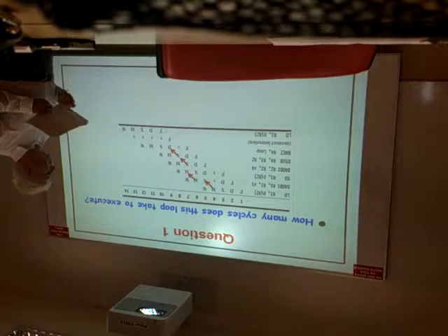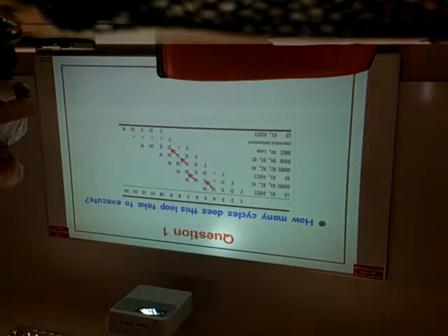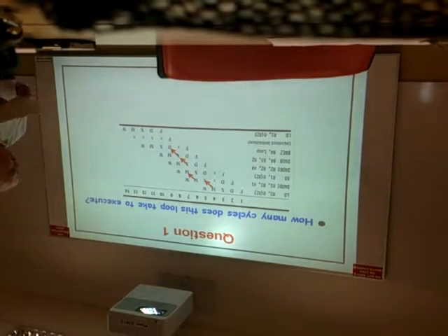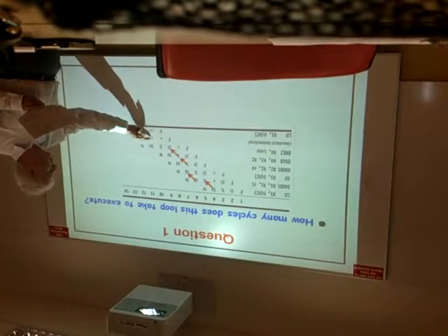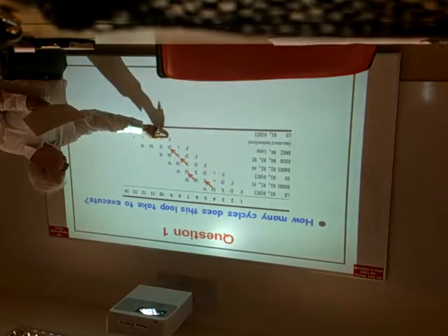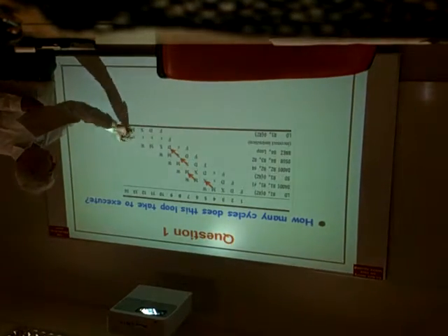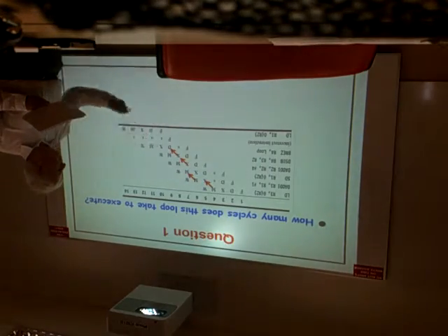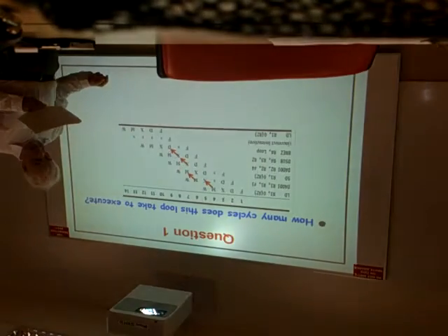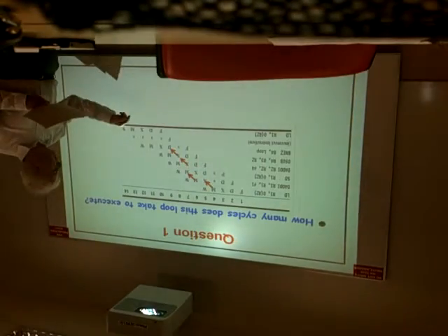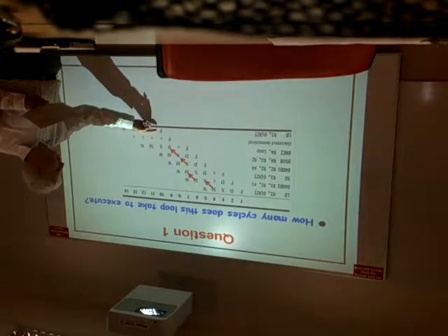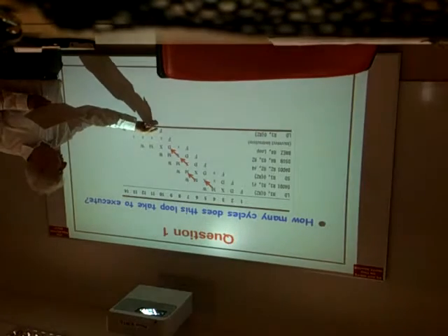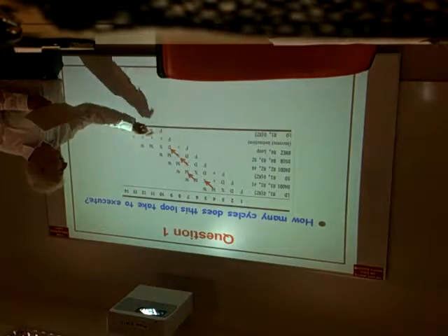And then for the branch itself, we predict the branch is not taken. So if we predict the branch is not taken, we will actually get the incorrect instruction. The branch is resolved in the decode stage, and the PC is updated in the decode stage, so we can actually execute the fetch for the correct instruction here.